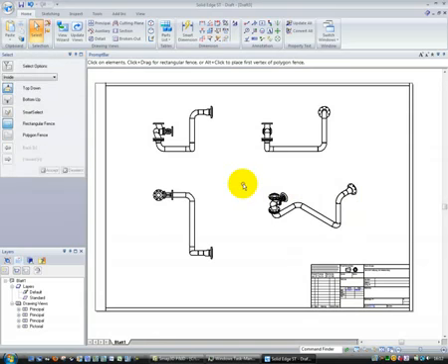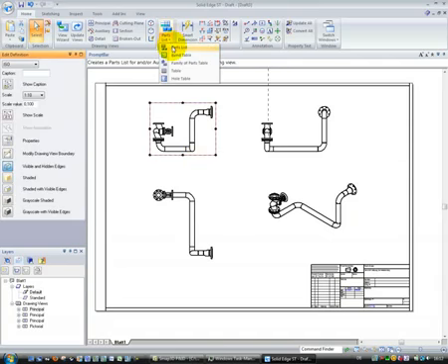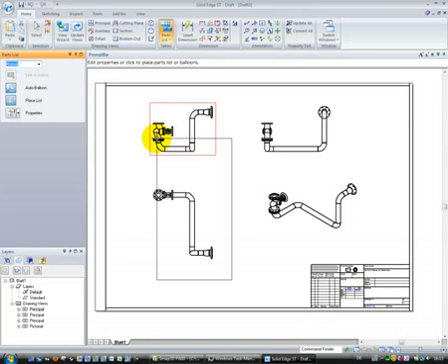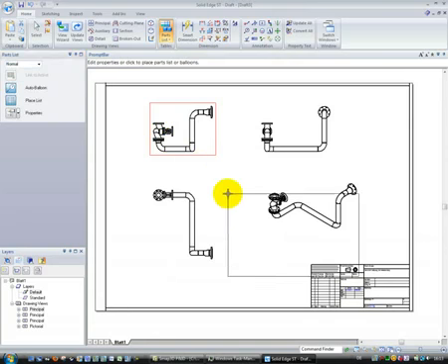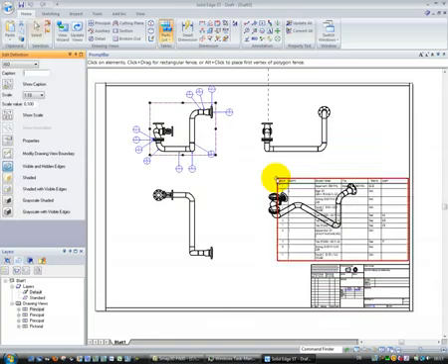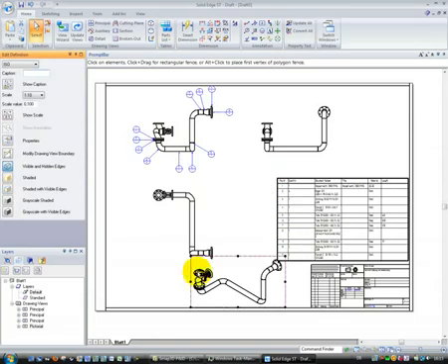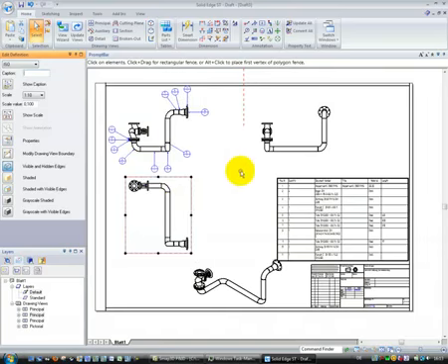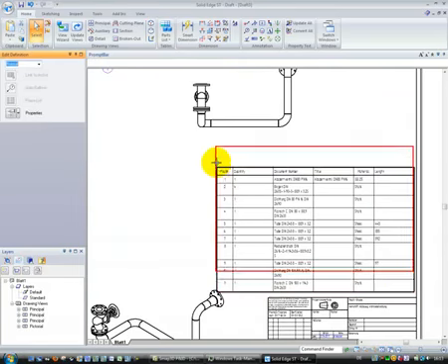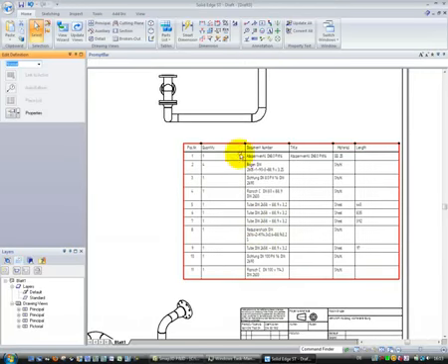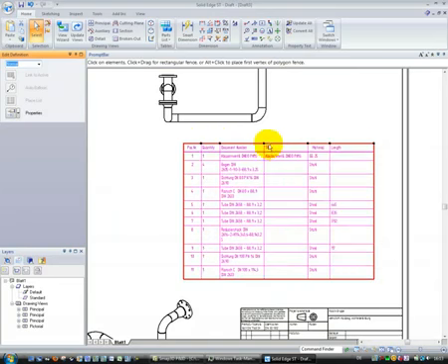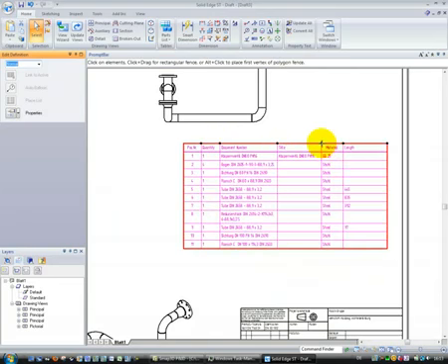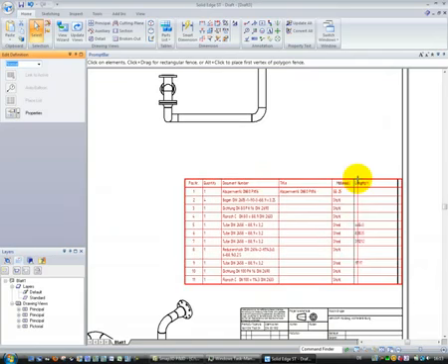So in this way we can create Solid Edge drawings, where we can also create, for example, part lists from these assemblies. And then we can place the bill of material, and all the content in this bill of material can be evaluated in the way that we use properties from the pipeline and from the piping software.